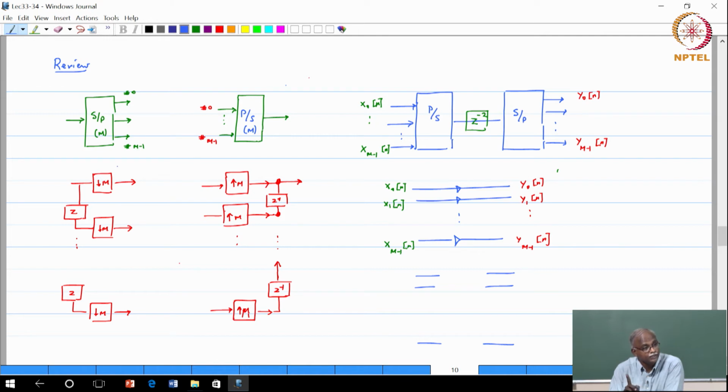That will be 0, because that we know, because if there is any non-zero delay between the upsampler and the downsampler, that will get killed. So, will this signal ever have a chance of coming to the output? Let us see if it will come through any of the other branches. If it comes to the next branch, it is upsampled by a factor of m, there is a delay z power minus 2, and then the next branch has got z.